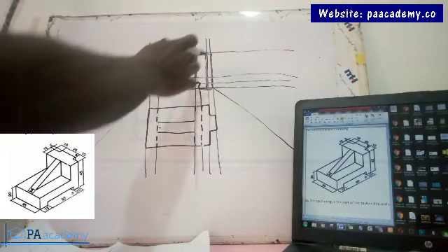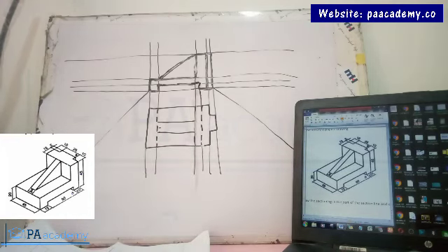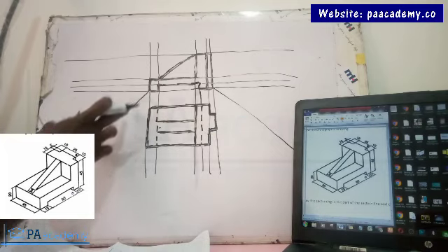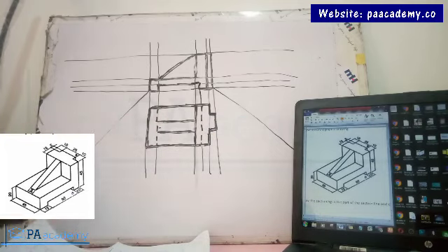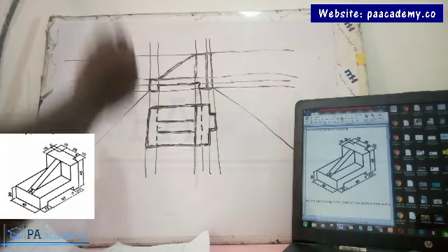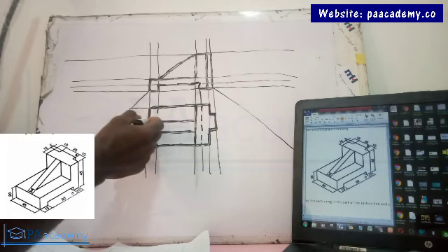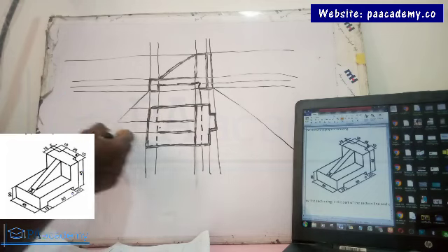Now the next thing is, just like we did here, let me make the main plan itself. Let me increase the thickness so that you don't get confused. All right, so I think it's better like this. Now the next thing you're going to do is to project all of these lines to hit, once it touches this line that makes angle 40 to this edge, you take it up. So something like this. Don't forget, they are all going to be parallel lines and they should be thin lines.